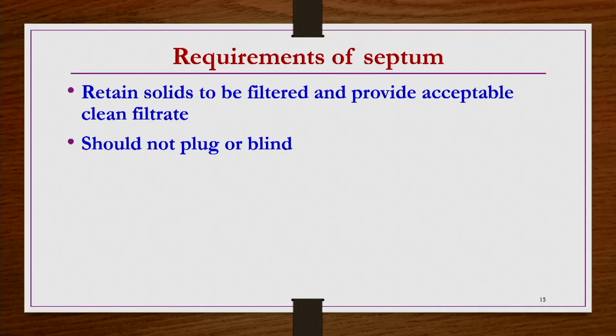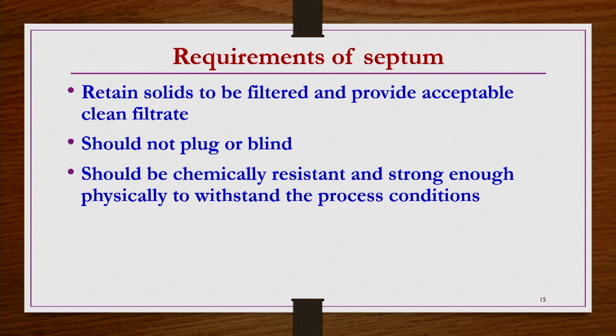So, because of that, the filter medium or septum we use should not necessarily just retain the solids, but should also provide acceptable clear filtrate, and should not plug or blind in general, otherwise the filtration process may be disturbed.